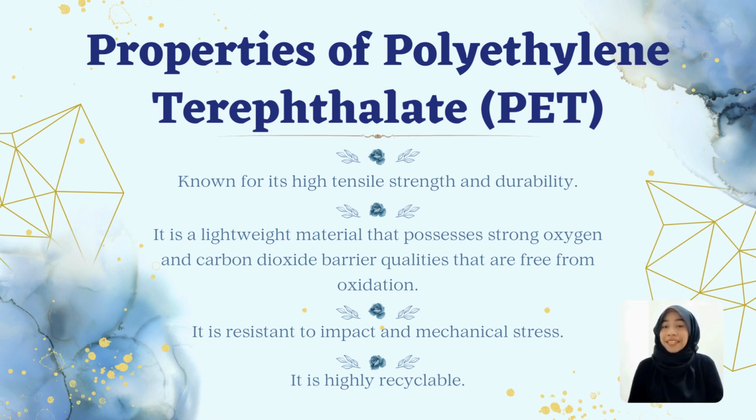In construction, PET is used in concrete construction to create green concrete, and it provides information about concrete's behavior and mixing design data. It's also used in construction, reducing the amount of cement used in cement making. To reduce the carbon footprint of concrete, some cement can be replaced with PET-based powder. The mechanical properties of PET were significantly changed by irradiation compared to non-irradiated waste. Using PET waste to replace a portion of cement greatly decreased the amount of strength loss.